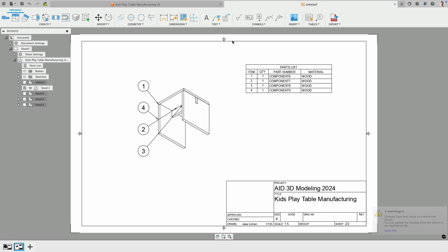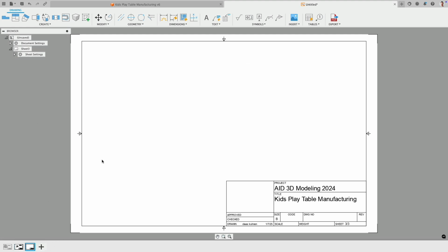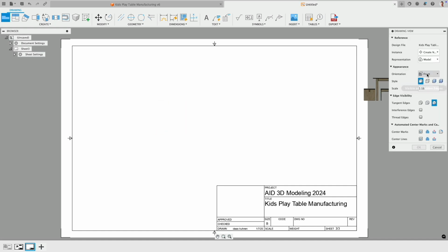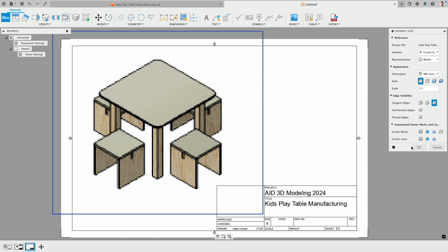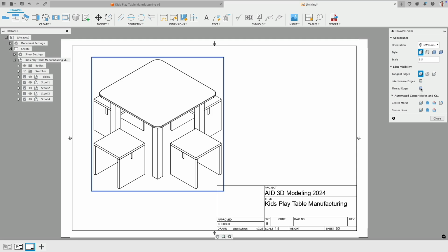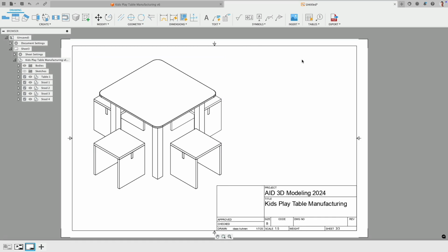When we go back and then do an update, there you see now the bill of material parts list actually updated. We have item 3 2 times. Cool. Sweet. Now, so you see, this is a very easy to use system, but it also takes a little bit of work to set up, which is why I think this is a really great tool to have and to use specifically at the end, but during the design process, for example, it might not necessarily be the best one to use because it's also quite time consuming.